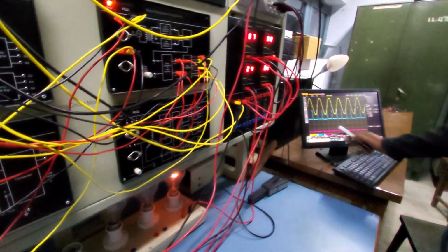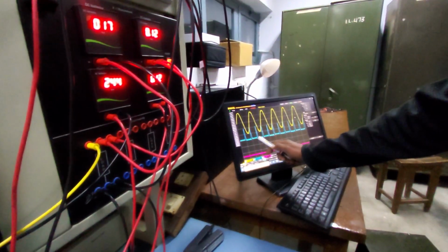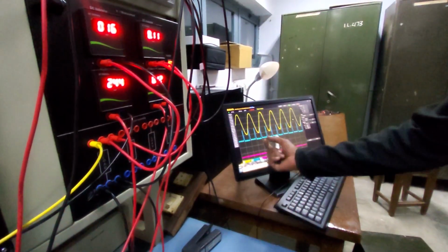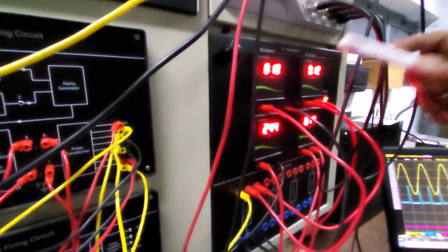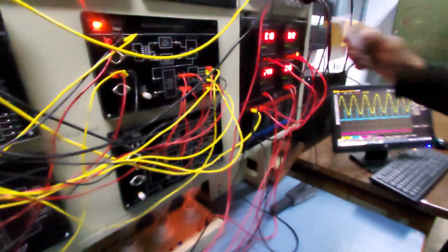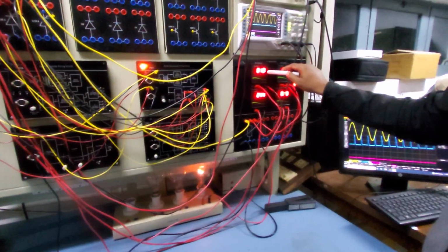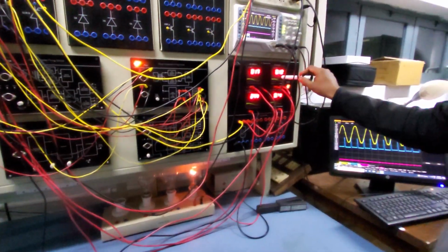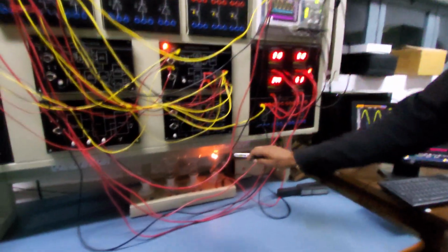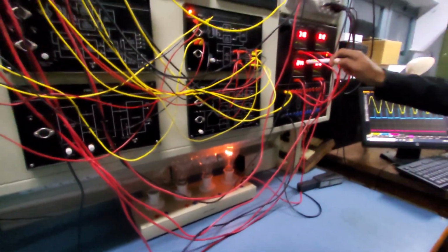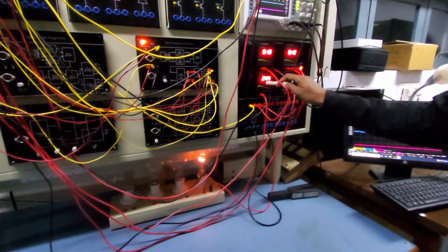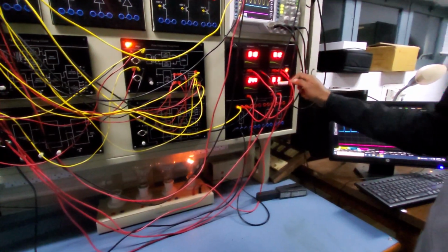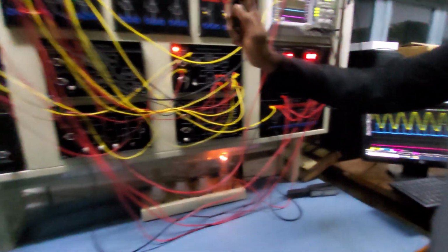Now you see here I set a firing pulse of approximately 160 degrees, so I get a small pulse at the output side. The output voltage you see here is 17 or 18 volt. So we get 18 volt DC output, and a current of 0.12 ampere DC flows through the bulb. The input voltage shown is the RMS voltage, which is constant at 244, and the input current depends on how you give the firing to that circuit.